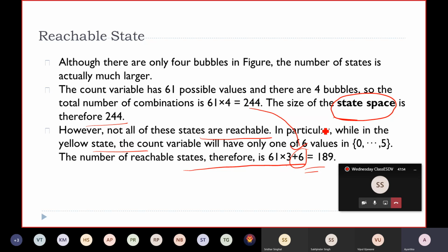My design may be huge, and some states may be wasted. In some scenarios, that may lead to huge waste. So of course, when we design, first we shall start with the worst case analysis of what the possible states are, and then the possible state transitions. But then we have to make one analysis based on what states are possible that will actually get active. Those are my reachable states.